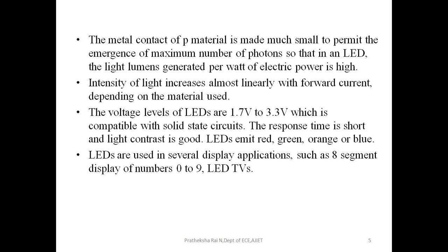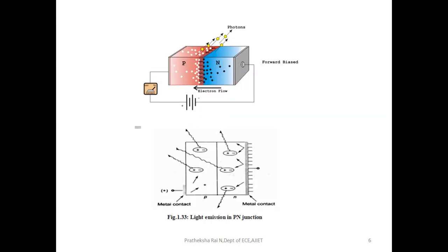Recently, blue and white colored LEDs are also available, but these tend to be much more expensive than the standard colors due to the production cost of mixing together two or more complementary colors at an exact ratio within the semiconductor compound, and also by injecting nitrogen atoms into the crystal structure during the doping process. Okay, so this is about the light emitting diode.